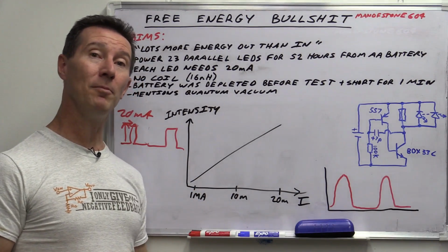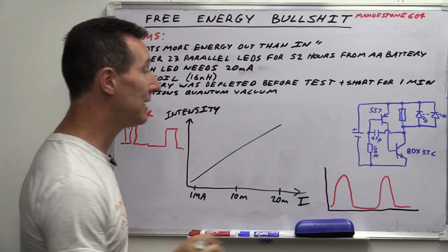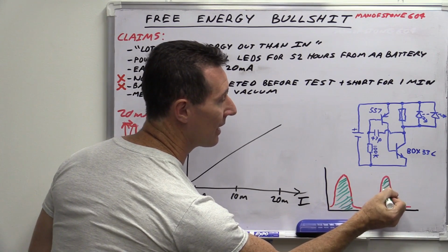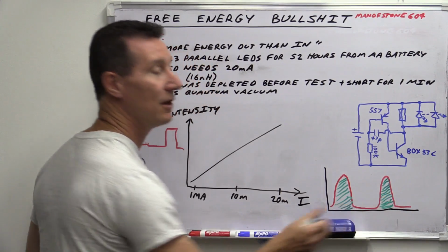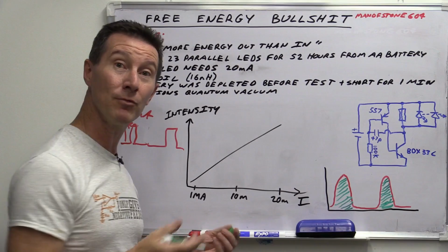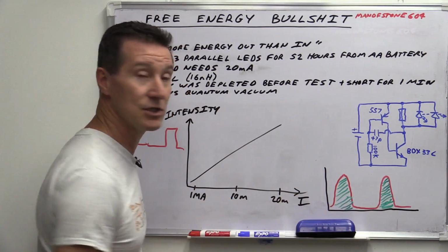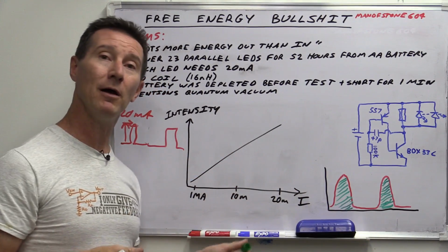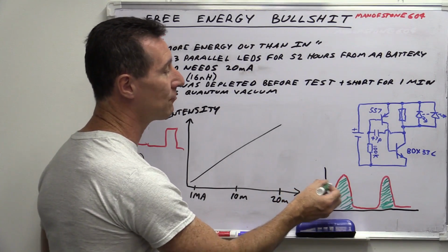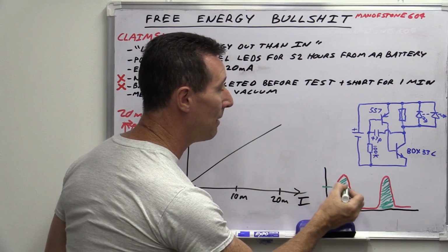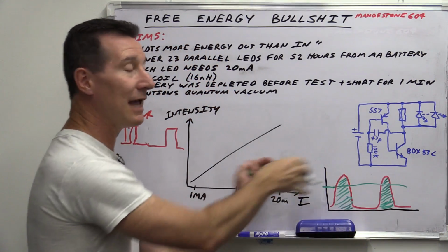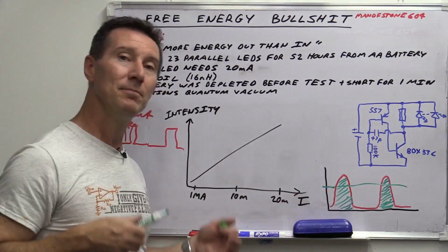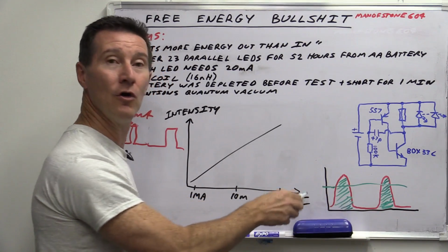And as I've done a video on before, the amount of power you're actually consuming in your LED is basically the area under the curve. It's the integral like that. So if it's a complex thing like this and it's not just a DC current, if you want the real power consumed in the LED, you have to get the scope shot of it and calculate the integral under the curve if you want to do really precise, proper, thorough engineering of this thing. But of course, you can just get your current meter, and it'll give you the average value over time. That's usually a reasonably solid result. But just be aware that it is actually the area under the curve, the integral.